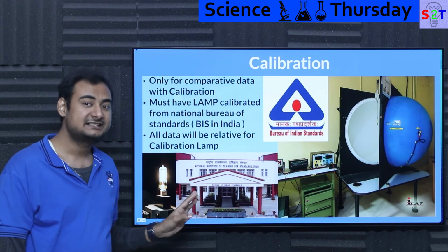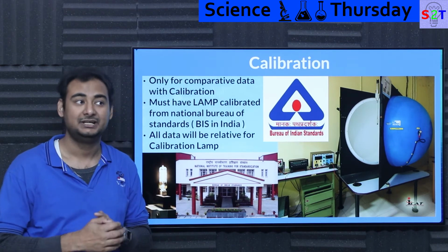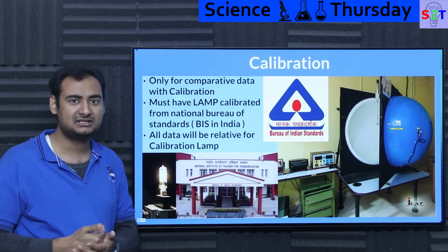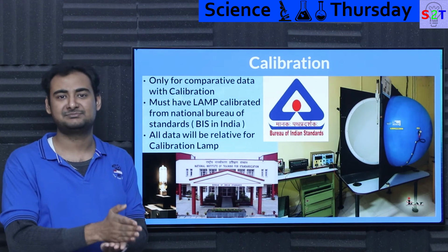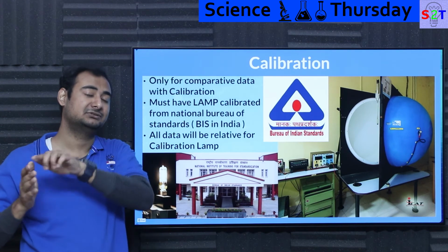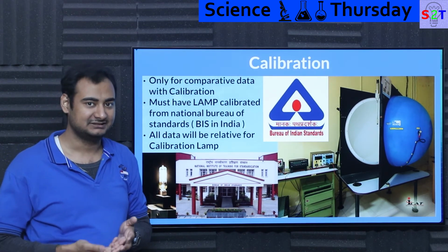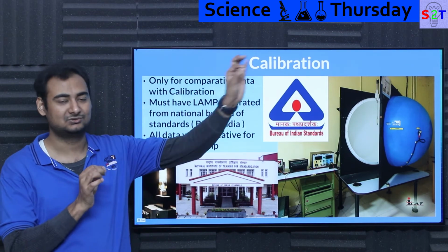So that's how you need that calibration, and that's why I specified they will always have an auxiliary lamp that also is provided. And you may even request, if you're really serious about this, hey, can you give me a 10 watt lamp, 20 watt lamp, 30 watt lamp? If you have this sort of granularity in your calibration, you can be damn sure, because sensors do behave differently. Very few sensors on this planet have absolute linear output.